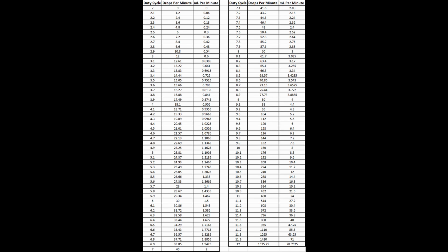To monitor the flow rate, instead, measurements were taken of the flow rate at each duty cycle of the servo motor, giving a range of values of flow rate at each position of the servo. These values would then be reported in the same way in which the values would have been reported had the IR beam break sensor worked as intended.